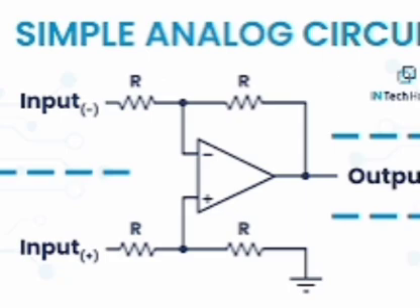Ripple factor of inductor filter for half wave rectifier: R equals pi RL in numerator, 2 root 2 omega naught L in denominator, where omega naught means source frequency. LC filter: pure AC input, rectifier, output across L, with C in parallel with RL. Ripple factor of LC filter for full wave rectifier: R equals root 2 XC by 3 XL. XC means reactance of capacitor calculated at omega equal to omega naught. XL means reactance of inductor calculated at omega equal to omega naught.